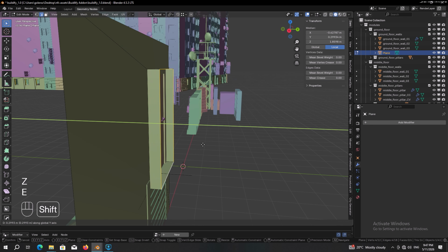So add it from our dear friend, the Archimesh. Add the rail window. Move it over here, and I actually like to rotate it by 90 degrees to have it from this angle. Then play around with the scale of it. Select the Boolean cube, shift select the wall, Shift Ctrl B, brush Boolean difference. Apply the modifier and select these new edges and extrude them backward like so.